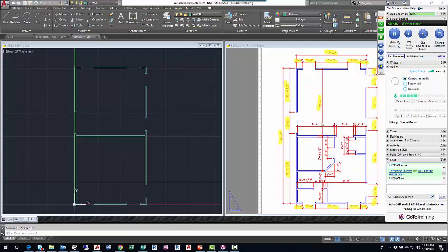One offset is 8 feet 3. That's the first one. The next one is not listed. The next one is blank because all walls are 3.5 inches thick. Then there's a 6 foot one. That's 3 so far. Then there's a 4 foot. The gap between the two walls is 4 feet. Then there's a 6 foot offset. And the final one is 3.5. So that's 1, 2, 3, 4, 5, 6. The 2 foot one, I shouldn't have to do.